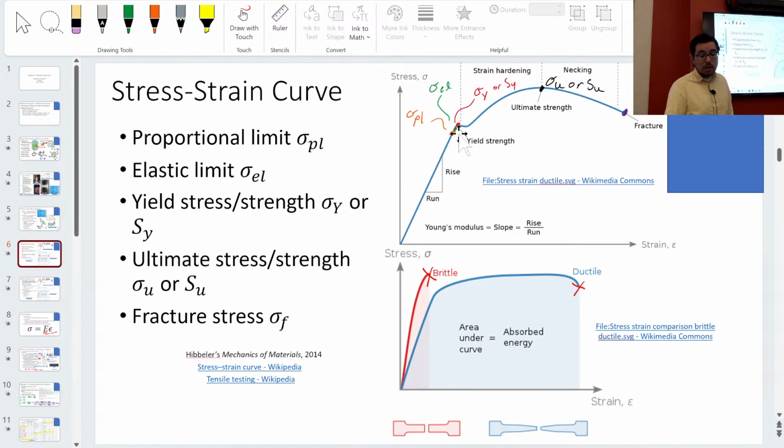If you go past the yield strength, proportional limit, if you go past the elastic limit, that's when you get permanent plastic deformation, okay? But if you go past the yield strength, which is usually past the elastic limit, that happens too. You'll see in steels, it does this interesting little dip, okay, and then it starts cranking up again.